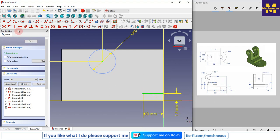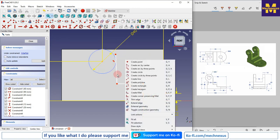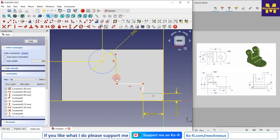After that I will draw a vertical line and then a horizontal line, and again a vertical line, but that would be tangent with our circle. So I will select this and give the tangent, and I will select this and I will give the vertical. And now I am going to the trim,